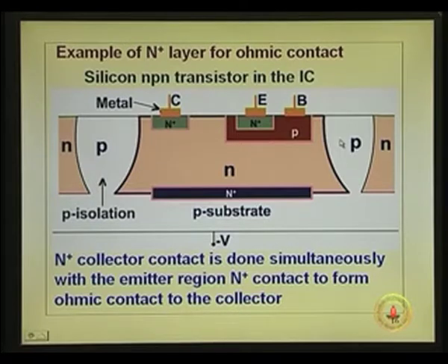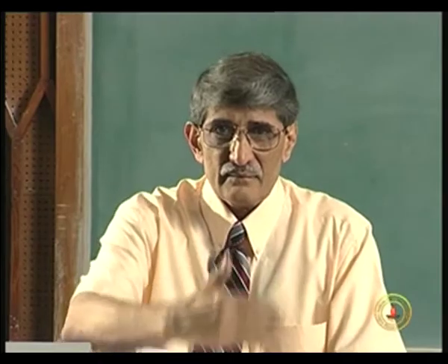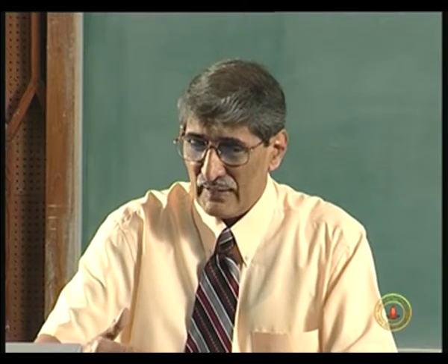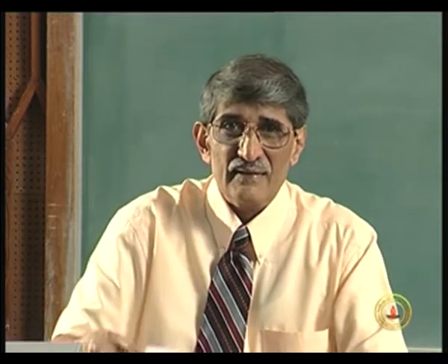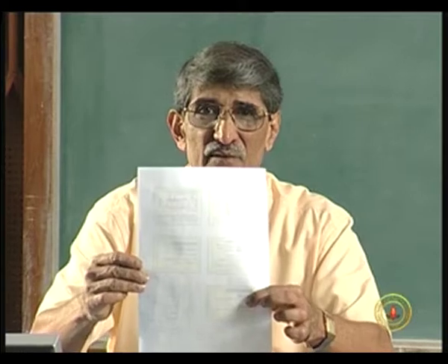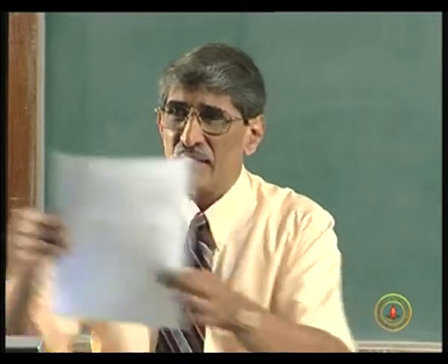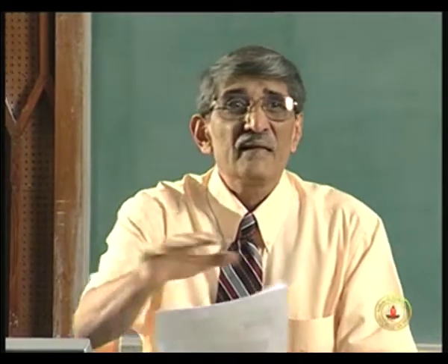Now, if you connect this layer, what you have got is this N layer, the cross section of that entire layer, that goes like this. The cross section actually goes like that. Top view will be like this. What I have shown is the cross section. So, you have got the island of the N layer like that. If you look from the top, you have got all through a P region, and another island coming nearby, separated by the P layer.